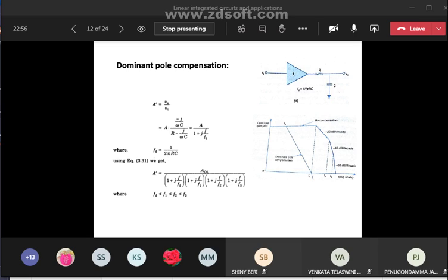Okay, so that is the gain of this circuit. So A equal to minus jXc, that is the voltage. See here, the impedance of this capacitor, minus jXc, by the total impedance R minus jXc.